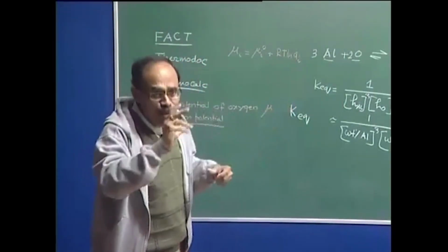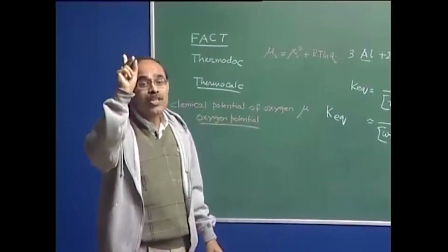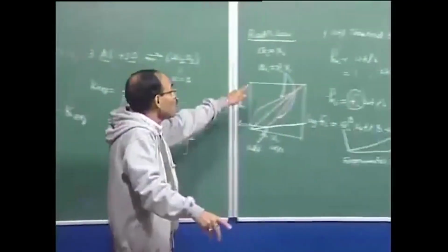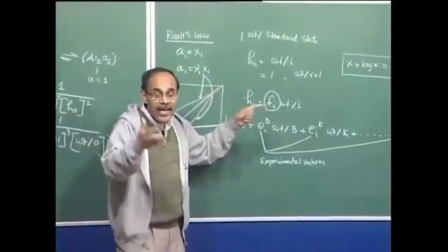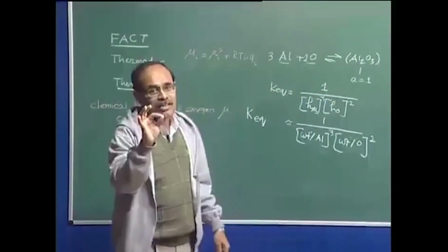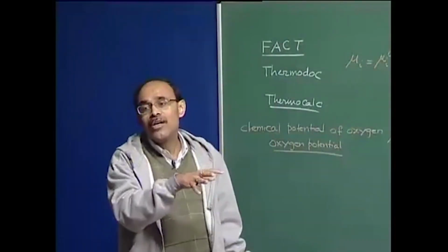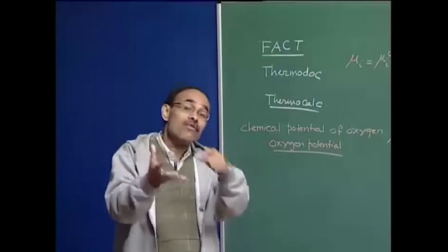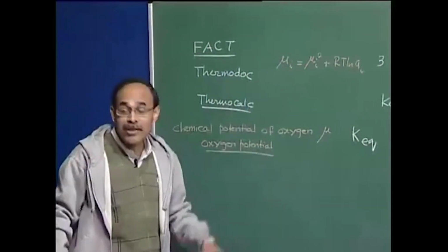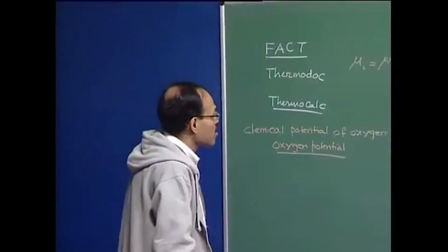This is because in the lower concentration region the activity of carbon is much higher, owing to the presence of many other solute elements which influence it through the activity coefficients and enhance the activity of carbon. So it is not the absolute value of concentration that dictates mass transport; rather, the possibility of transfer of a species from one phase to another is dictated by the chemical potential. Therefore, chemical potential is a very, very important term in the context of mass transfer studies.